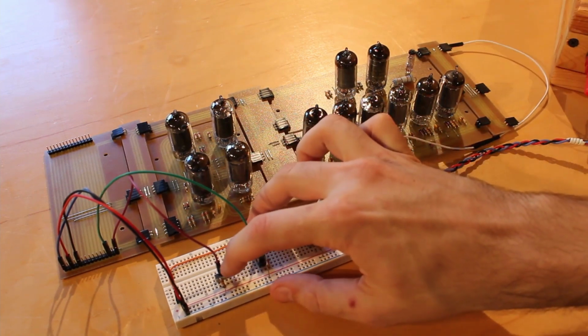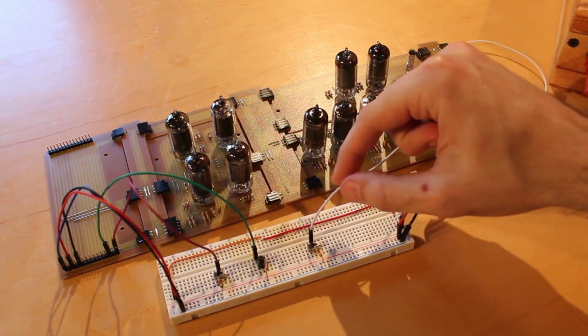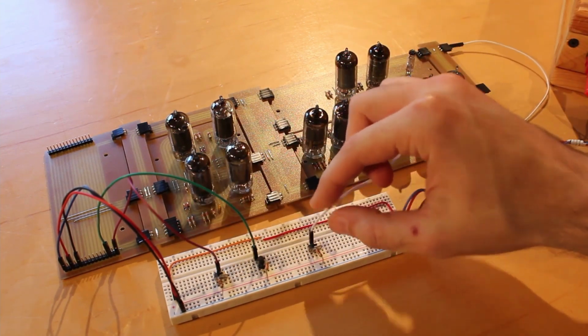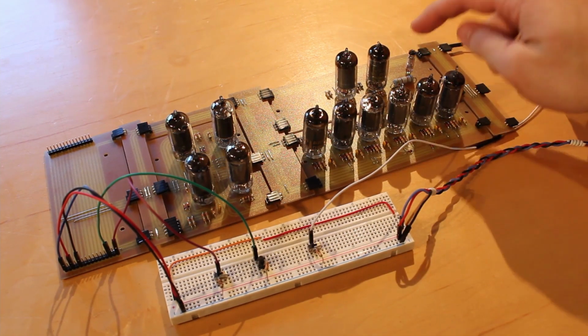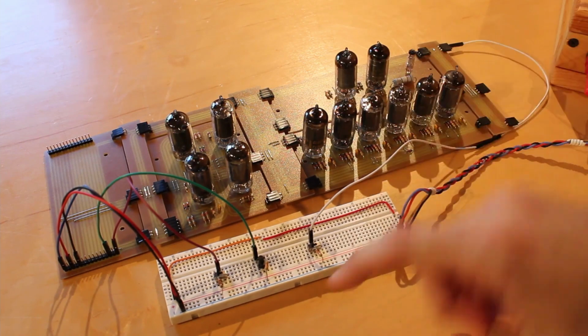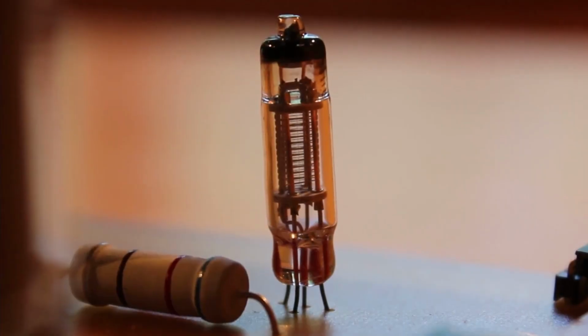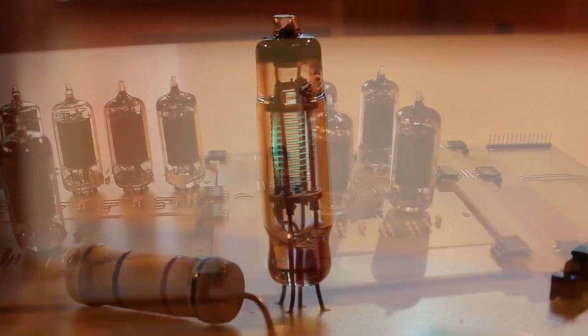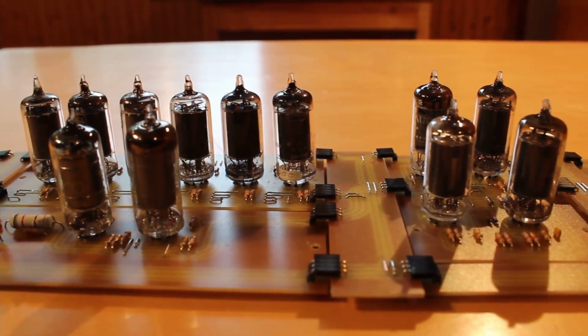So here we go. Moment of truth yet again. Both our data is on and our 1010 instruction register is on. So if I hit this clock, we should see this VFD illuminate, which tells us that we're now storing a 1 in our input enable register. Yes, look at that. Awesome, our VFD kicked on. So now we know that our input enable register is storing a 1.